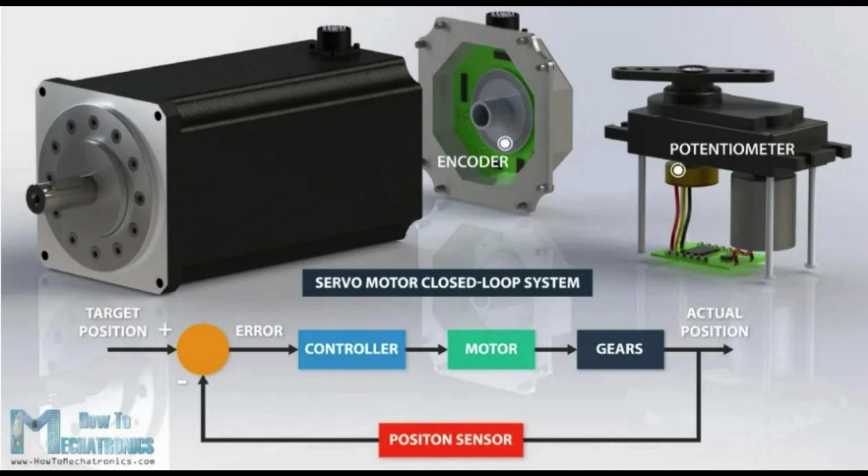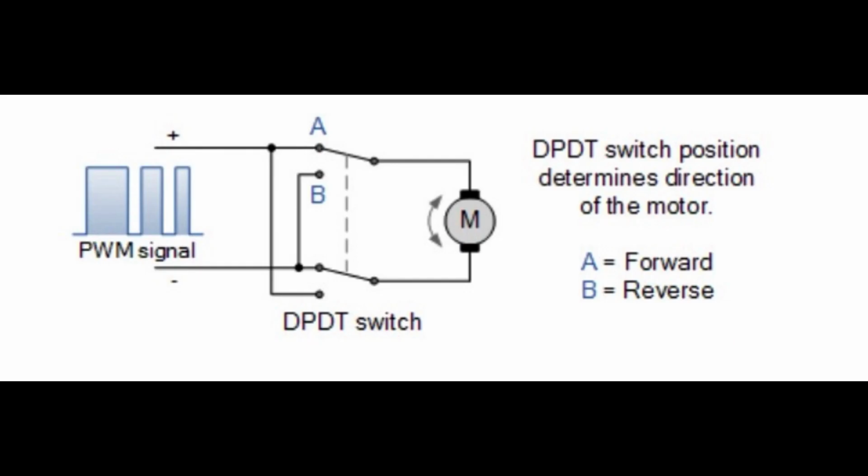There are two ground numbers, one and two. So to facilitate easy movement of the garage door, we can use two servo motors on ground number one, on either side of the door, with sensors attached to the entry floor and the rooftop to determine initial and final position. Servo motors can be rotated in both directions using microcontrollers having double pole, double throw switches or bidirectional H-bridge DC motor circuits. The mechanism can also be manually operated by attaching a handle at the front part or by manually rotating the crank.